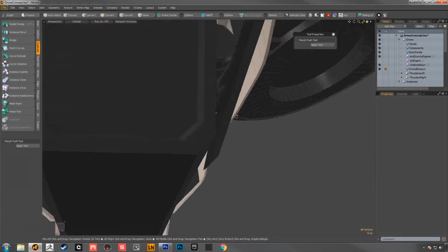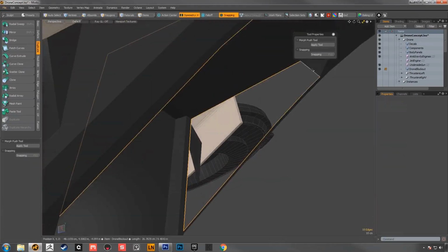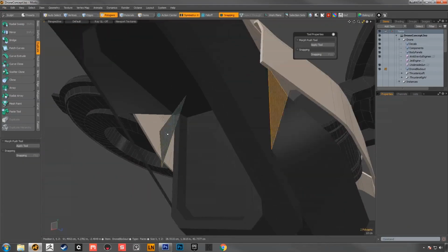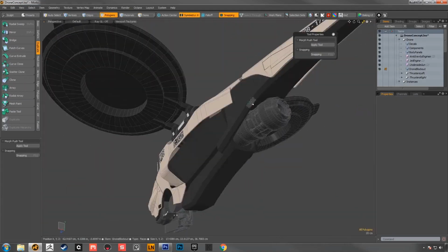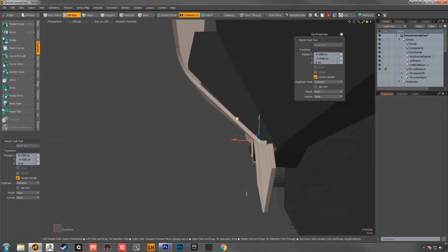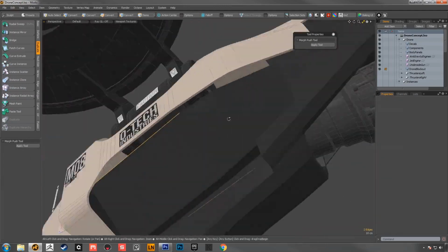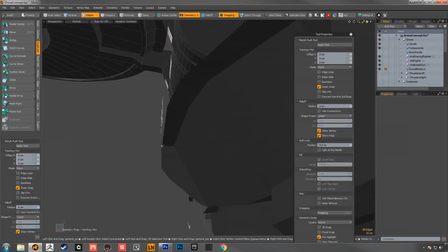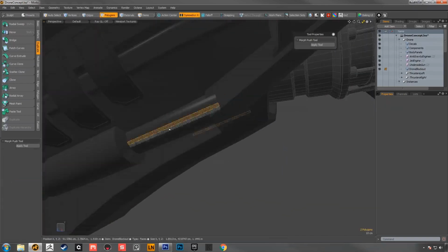So this is all about modeling the housing for the vents that would sit around the afterburner, but also the housing for the afterburner itself. It's really about tidying it up so that I know the only stages left for those areas are to go in, add those single-sided bevels, do the force normals, which is very fast, UV it and apply materials, and then I'm done.